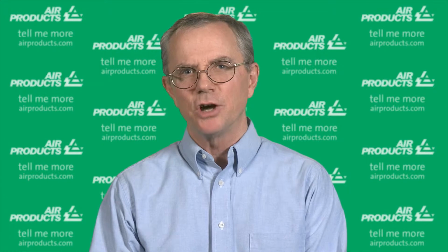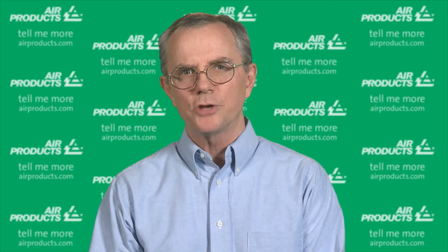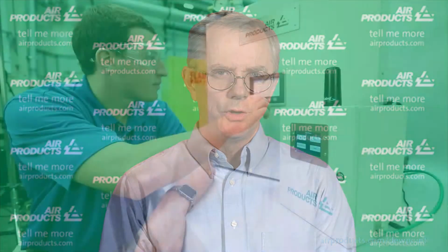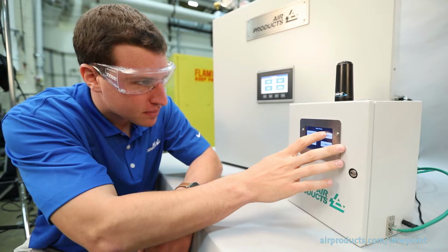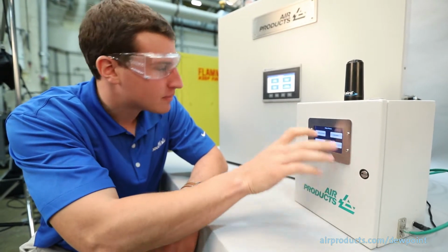Dew point is a measure of the moisture concentration in the furnace's atmosphere. It is one of the most important process parameters, so its accurate measurement is key to understanding what is going on in a furnace. There are many ways to measure the dew point of a gas sample. Most common industrial dew point analyzers use a capacitance-based sensor with an extractive sampling system.